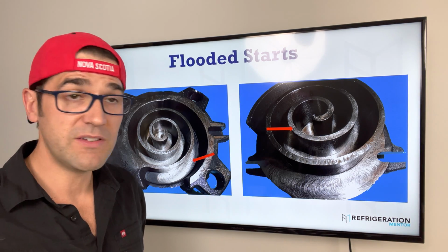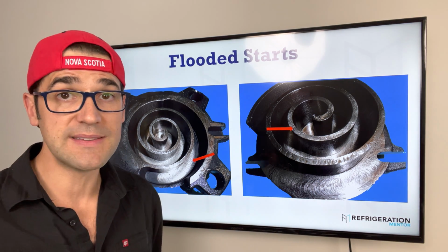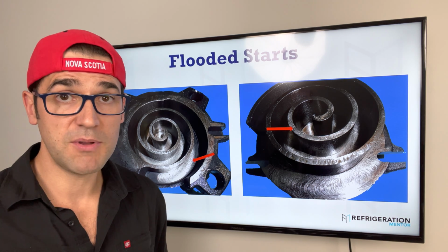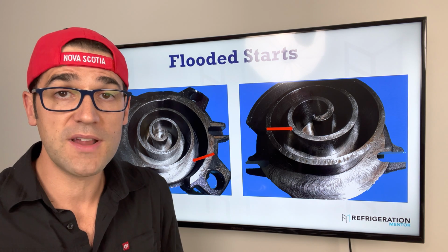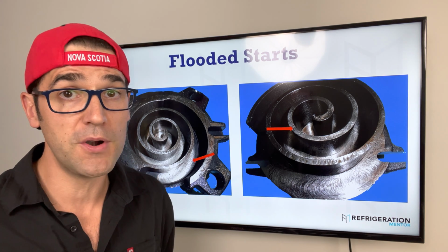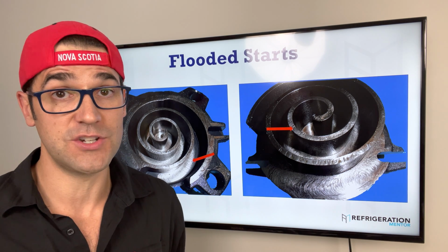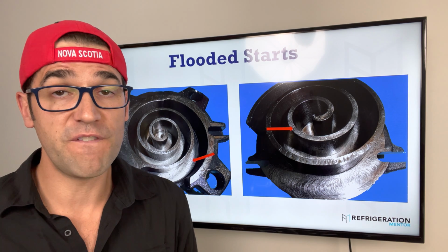Once again, flood back is still bad, even minor ones, because you start to get this wear on wear, metal on metal, and what could happen is that metal falls down into the stator and you get a short. And we've talked about this last time. A lot of times you're going out there and you're ohming out those compressors and you're getting electrical failures, you're getting burnouts. But 80% of the time, that is caused by a mechanical issue. And that mechanical issue is causing the electrical failure.